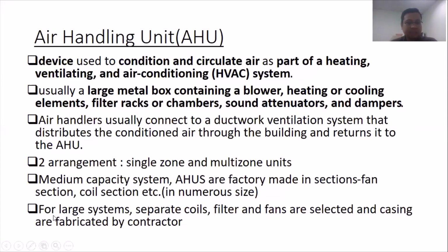For large systems, separate coil, filter, and fan are selected, and casing are fabricated by the contractor. So sometimes the contractor is used for big size conditions, and then they separate coil, filter, and fan, selected based on what the contractor needs. So the factory will fit it inside.